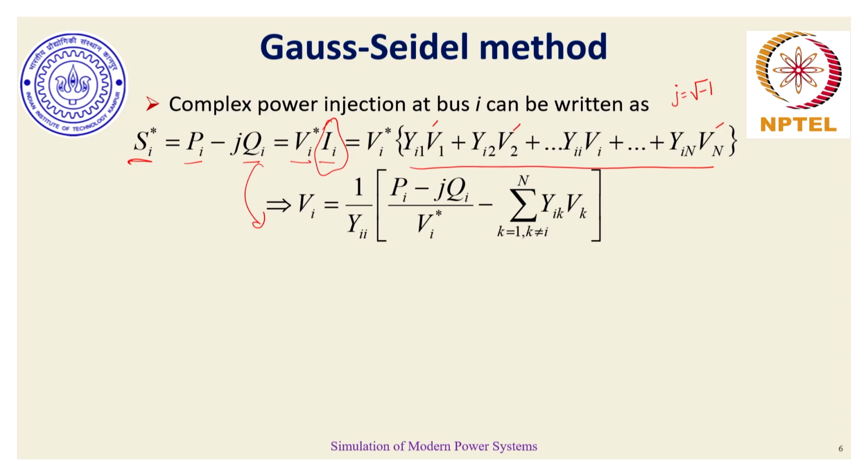And in this form, what I can now do is, in order to obtain this mathematical form, the Gauss-Seidel method works under certain conditions of mathematical orientations. Essentially, it is all to do with the initial choice of voltage phases that we choose, because essentially these are nonlinear equations. Any iterative or recursive technique would require a good initial choice so that the final solution can be easily obtained, as direct closed form solutions of voltage and phase angles are not possible till date.